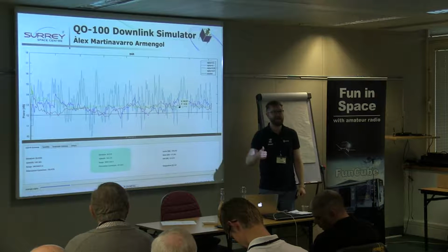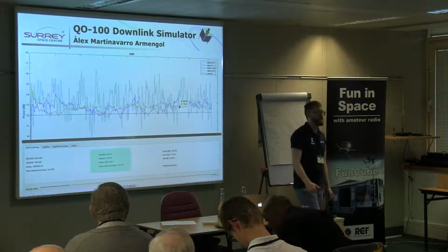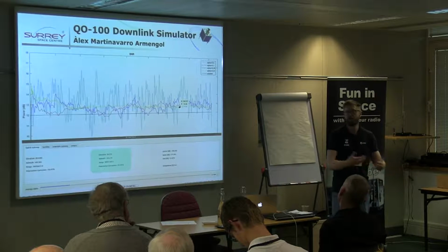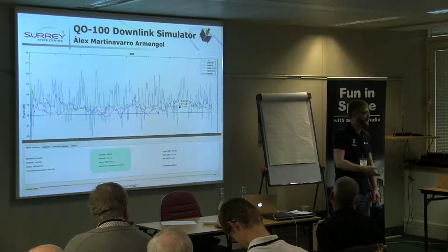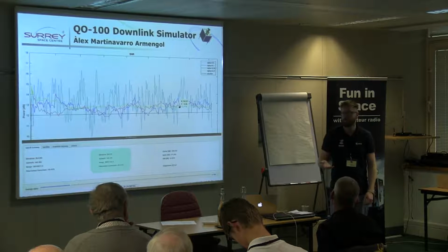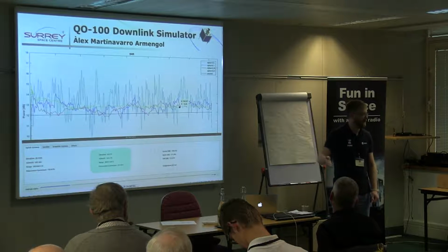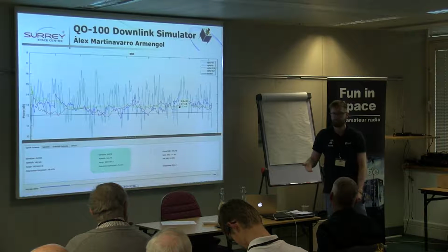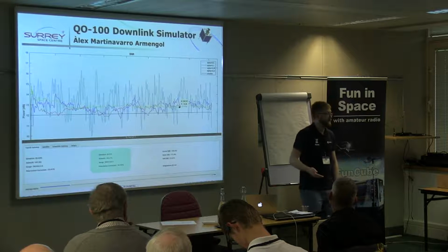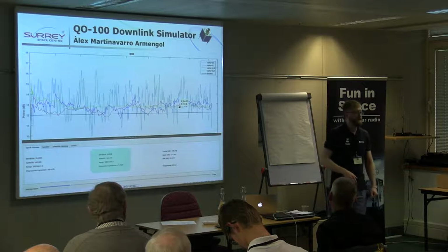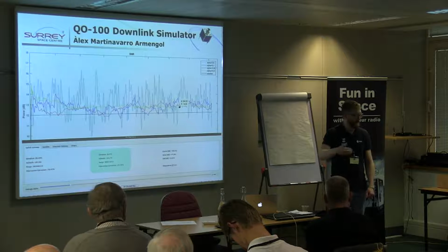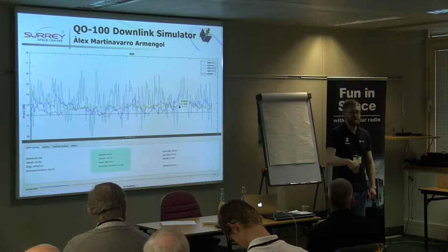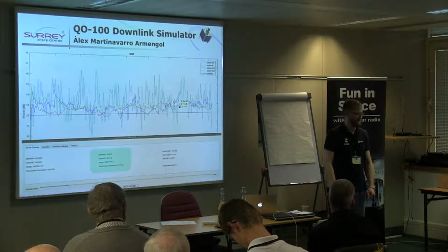The things that, for instance, he hasn't modelled in here are things like circulators, or if you've got more than one antenna plugged to the same thing, splitters. Theoretically, some of these things we assume, minus 3 dB. Well, that's based on a system noise. There's an actual linear relationship to that, and you can physically go and measure it. And of course, these sorts of tools can then be used to monitor how your own ground station is performing. You should know what it physically is doing, and if it starts to deviate, then which part of it has gone wrong.